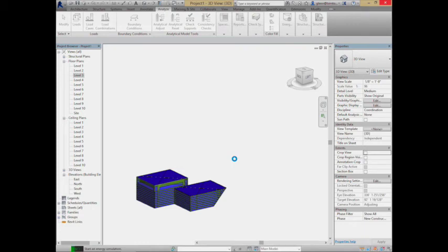So we can play with all these different things. The glazing percentage, we can play with the amount of insulation in the walls. We can also start playing with the shapes. And really, if you think about it, for any building of a set area, let's say we had to come up with 400,000 square feet, we can come up with that a number of different ways. I could come up with a building which is very flat. Very big, but very flat. Maybe it's only 2 or 3 stories tall.